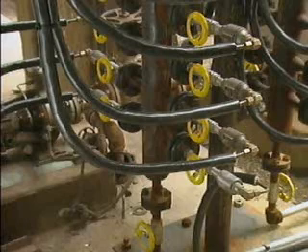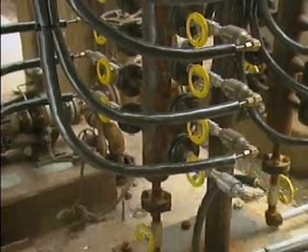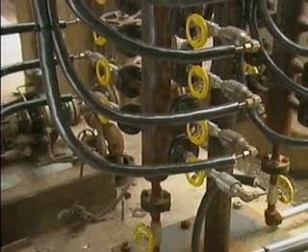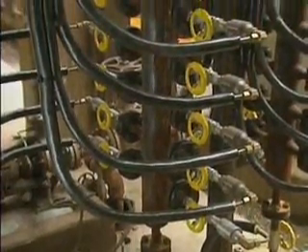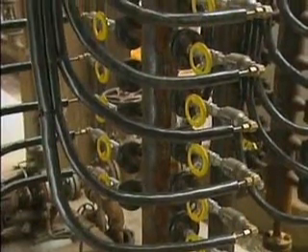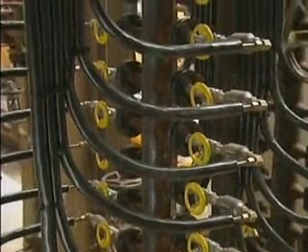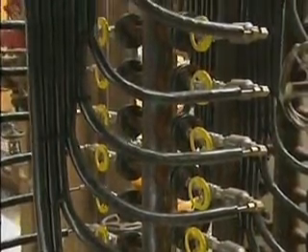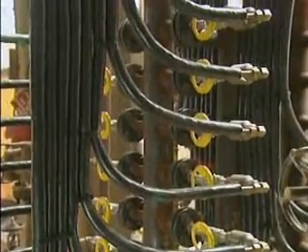Trap surveys based on differences between trap inlet and outlet temperatures can be inaccurate in certain situations. For instance, if a series of traps are installed on a manifold setup so they discharge to a single return line, back pressure may rise because of faulty traps. But the back pressure will rise on all the traps in the system, good and bad alike.